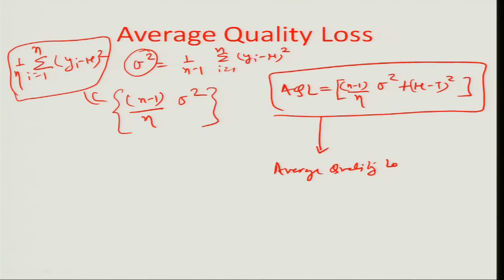Now the question is whether really this is the average. There are some quality parameters which are desirable and there are some quality parameters which are undesirable. For example, let us say if we are talking about vibration and noise in an equipment, that is an undesirable parameter, vis-a-vis a parameter where you are talking about, let us say, the dimension of a shaft. So, when we are talking about a quantitative parameter like the dimension of a shaft and how much away it is from the target, the average quality loss probably makes sense. But when we are talking about an undesirable characteristic like friction and wear, where the minimum possible the better it is, in that kind of a circumstance it becomes a little difficult to understand this as the deviation from the target.